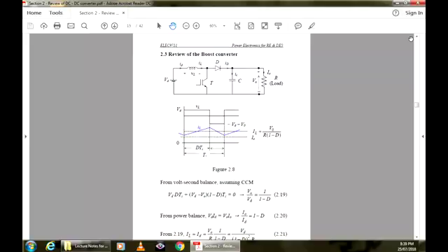And during (1 minus D)Ts, current must fall to the same value as previously. Otherwise, there is a DC current here and also an AC voltage across the inductor, which is not possible.